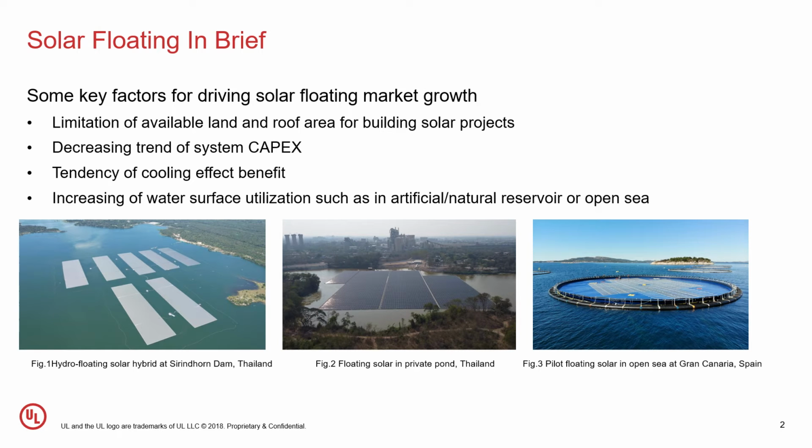Recently, solar floating continues growing in many countries, and here are some key factors that drive the market growth. Number one is the limitation of available land and roof area for building solar projects. The second one is the decreasing trend of the system capex. It is driven by the lower cost of the pontoon.